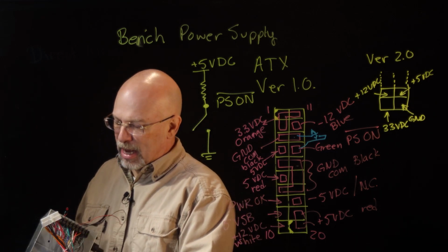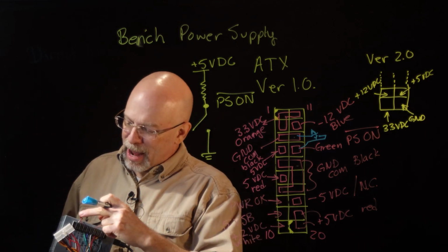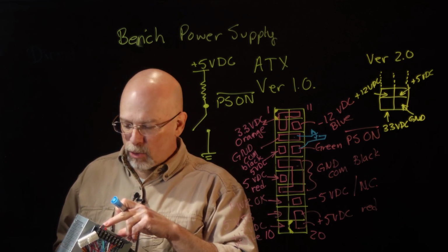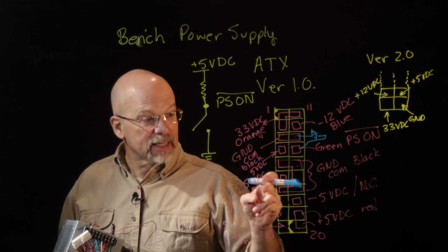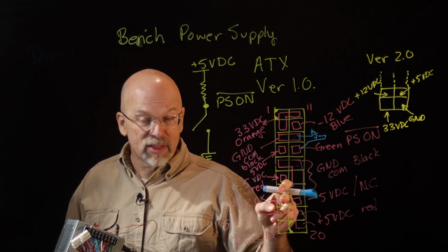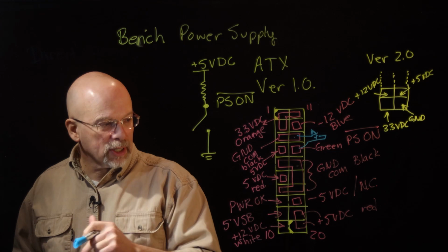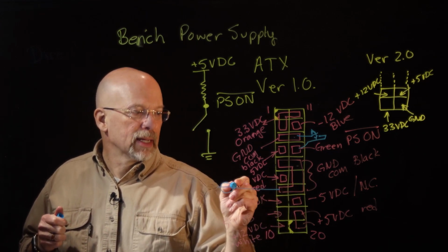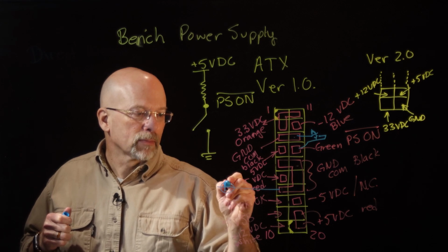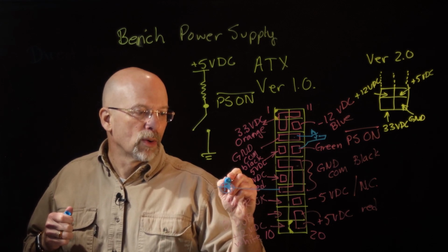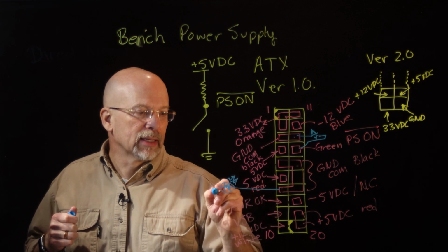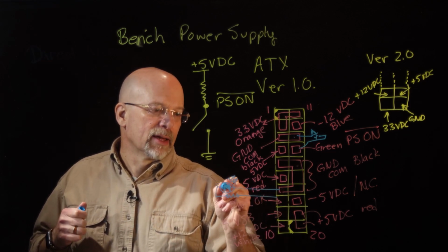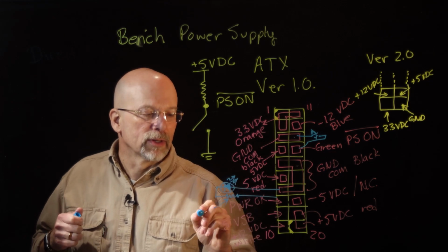So what you can see, and you probably can't see it from where you are, is that I have an LED, and I have soldered to it a small 220 ohm resistor, and it's simply connecting between this pin and this pin. And so your circuit is going to look a little like this. Out of this is going to be an LED. So I'll just put a symbol for an LED, and then it goes through a resistor, and I drew my LED backwards, but you can hopefully get the idea.